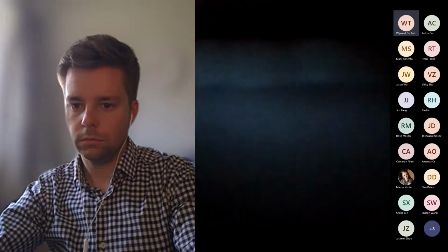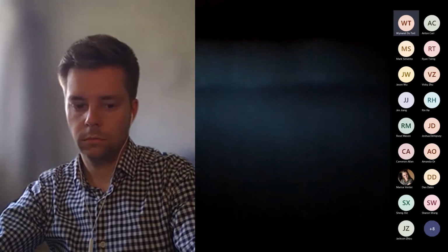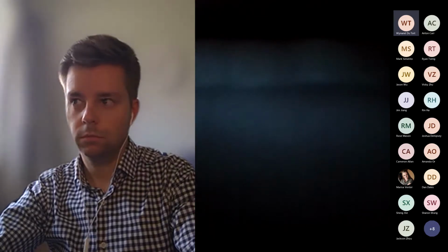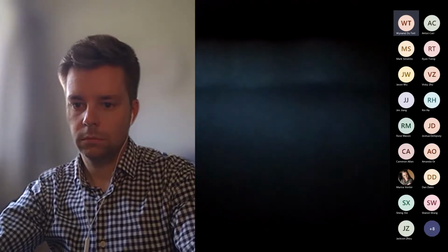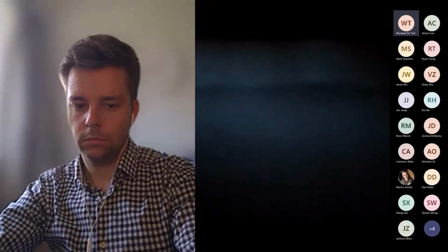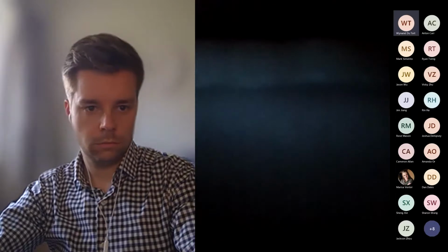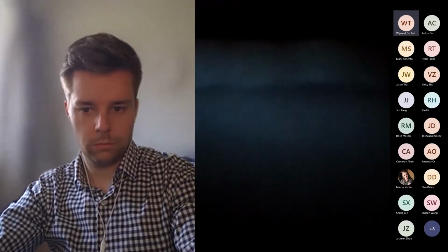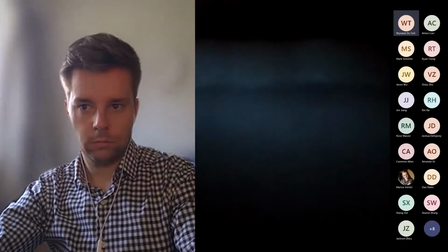As the snippet that Matthew showed earlier on, any flows exceeding your design treatment flow rate need to bypass your treatment section of the system. So it needs to be diverted externally from where your cartridges or your media is sitting. I just want to clarify that, Matthew.